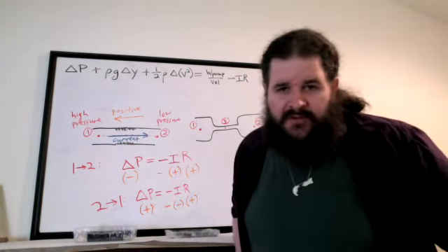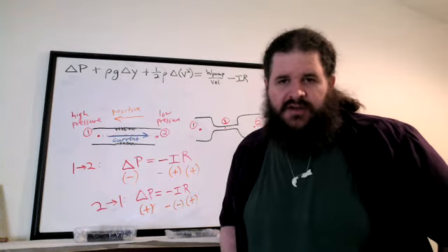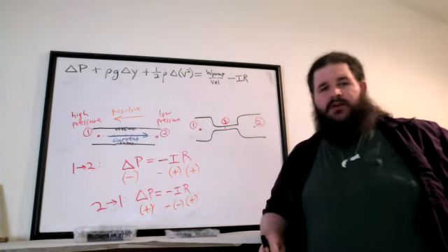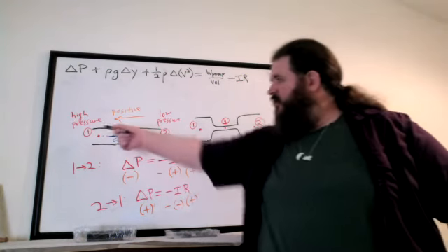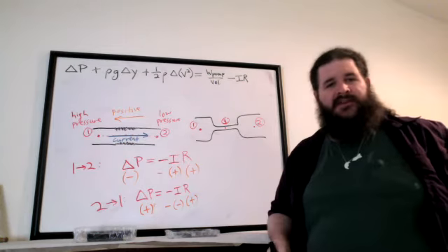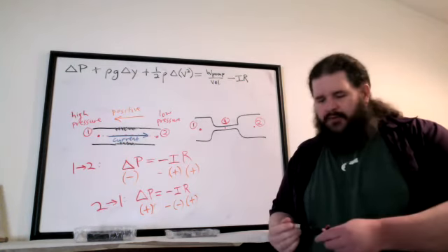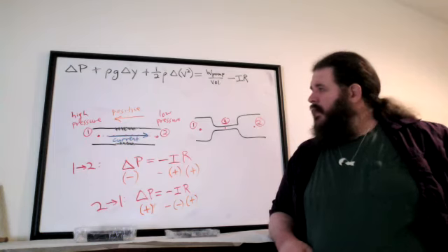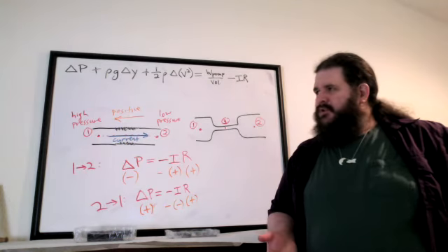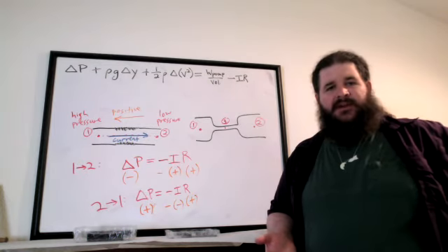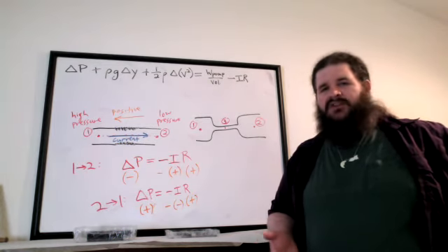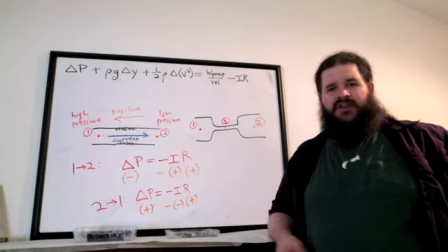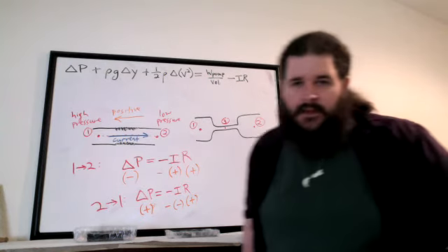In a problem when they specify, usually not. If you already know which direction current is flowing, it's usually easiest to just treat the direction current is flowing as positive. If you don't already know, just make your best guess or just choose a direction to call positive. And if you guess the direction that current is really flowing, you'll end up with a positive value for current. If you guess the opposite direction, that's fine. You just end up with a negative value for current.